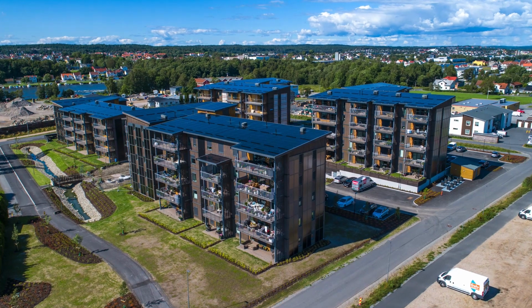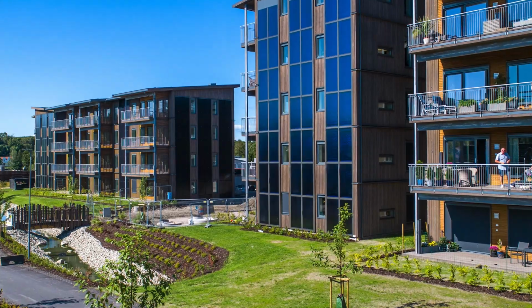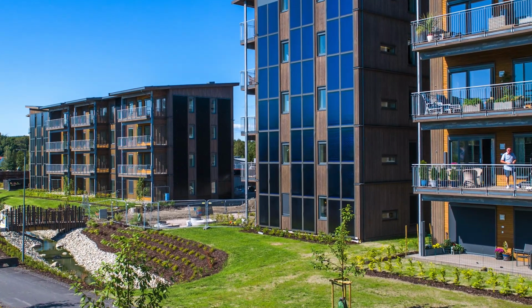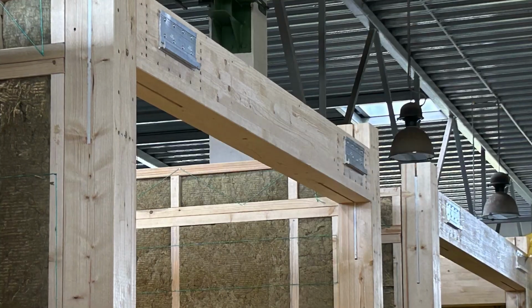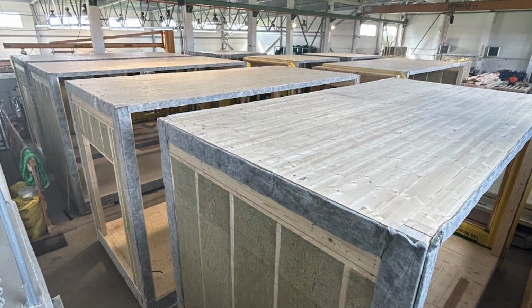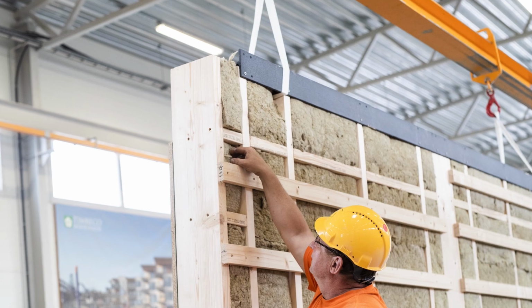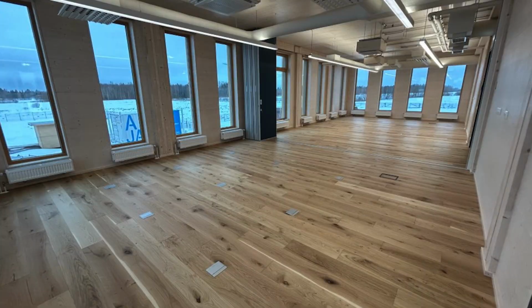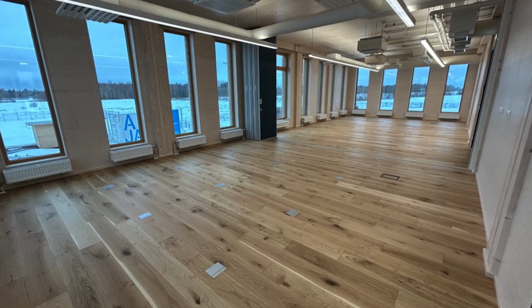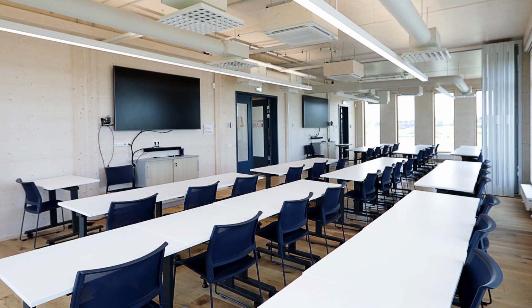In the case of taller buildings, situations may also arise where a strong wind load affects the frame structure of a building to such an extent that, in order to increase stiffness and stability, some of the boundaries must be made of CLT elements, engineered wood, or even a steel frame. Such hybrid solutions in modules are central to a single building, and the structure is calculated according to the loads acting on the building.